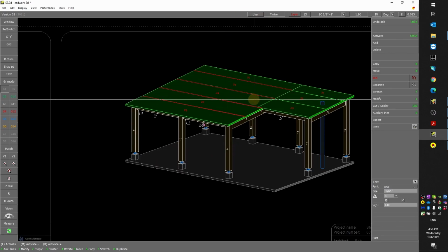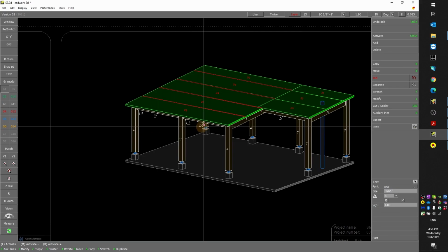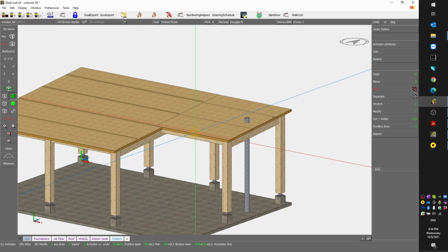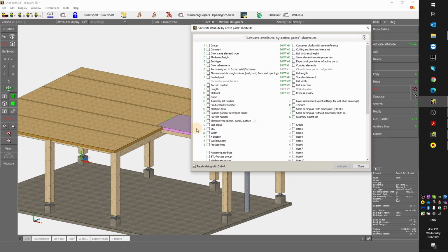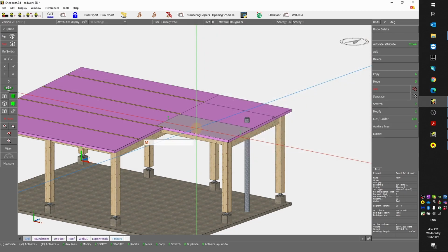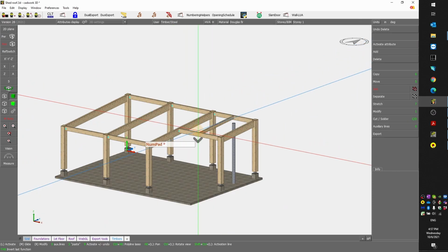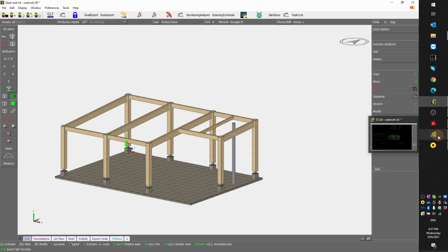Here in this case, eventually we would only keep the panels on top and not include the glue clamps. So that's another view that I could export. I could activate all my panels, Control A. Let's say M for material. I want to hide the splines as well. And now I can export the data. So again, semicolon and export. So basically what you see is what you will be exporting.